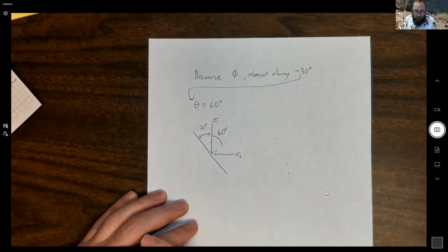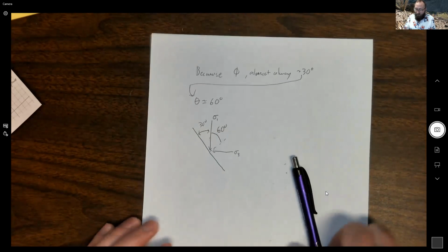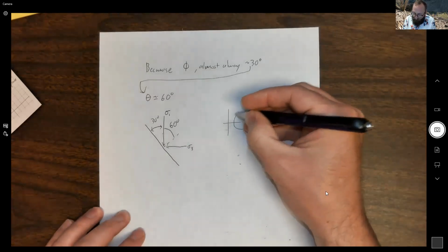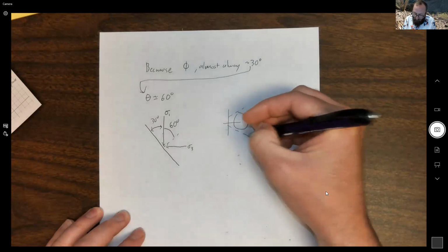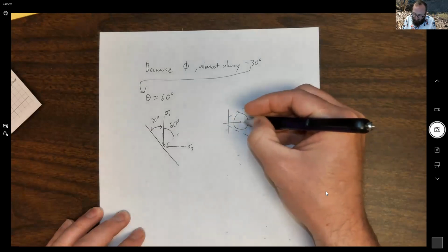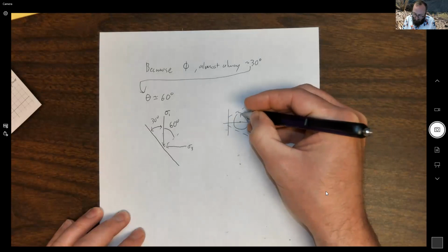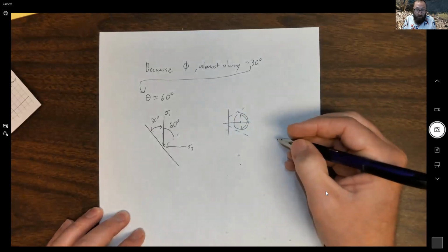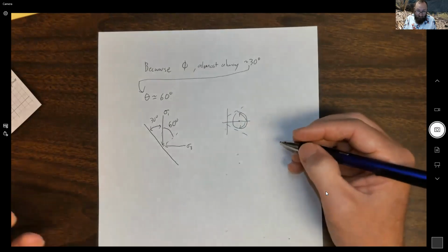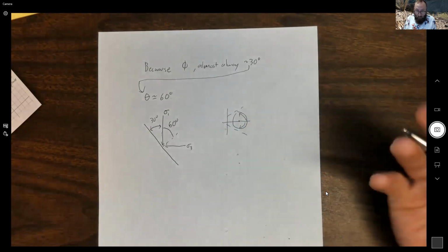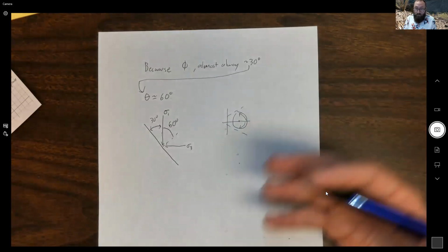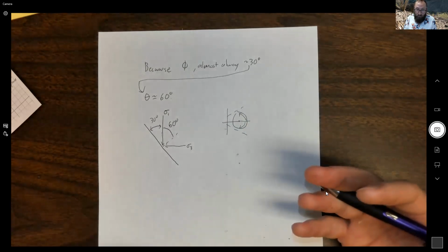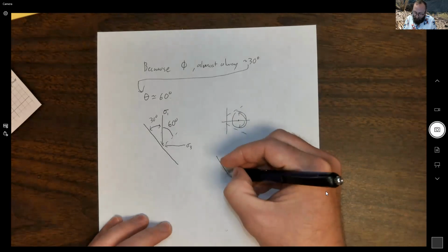Okay? And because on our Mohr circle diagram we could go from the center part clockwise or counterclockwise to failure, essentially because theta can be positive or negative, we always end up with two fault orientations that are predicted, which we call a conjugate fault set.